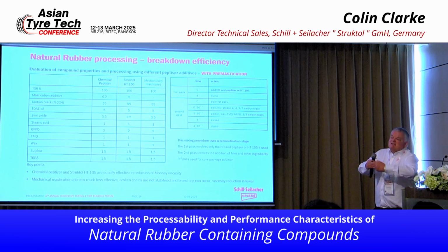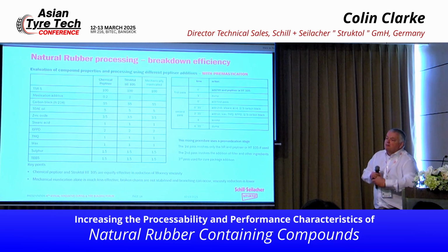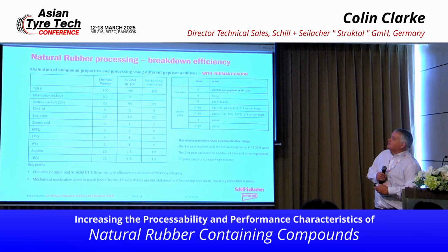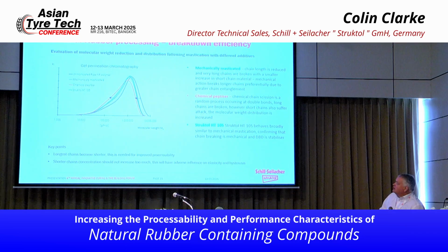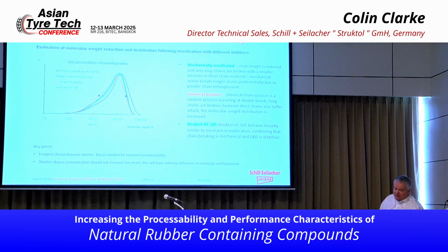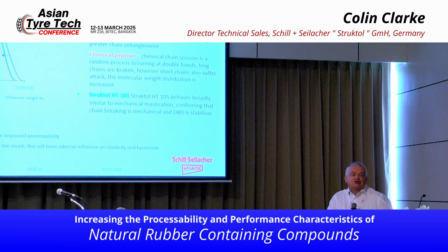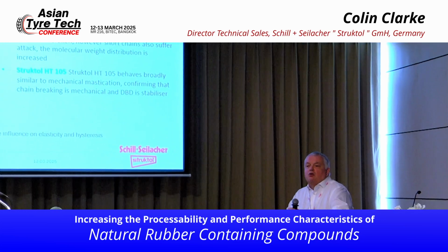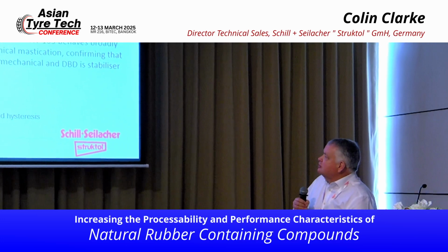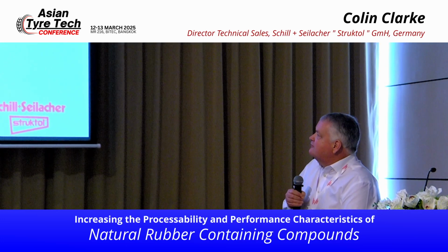So that's the very traditional, more time consuming, more energy consuming, three-stage mixing, if you like. Actually, when we do that and we look at the first stage of mixing, just the rubber mastication, we can measure the molecular weight reduction. So not only Mooney, but also what did we really do to the molecular weight. So these are the molecular weight distribution curves.